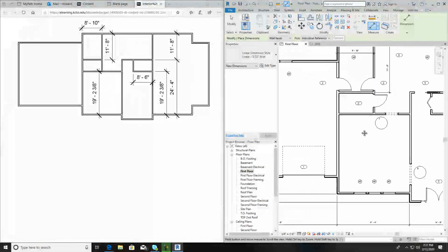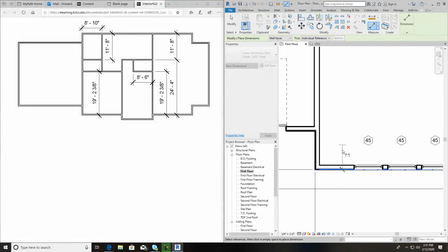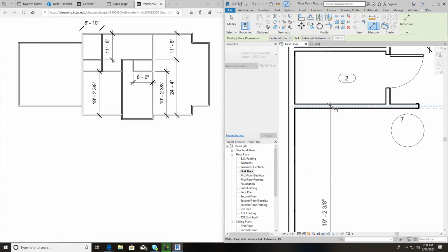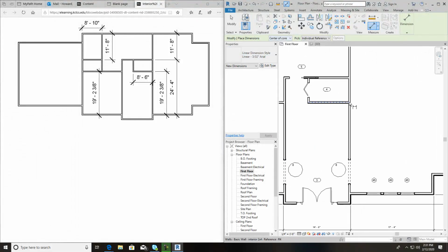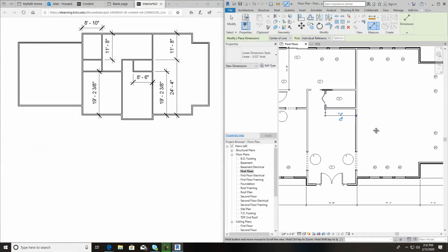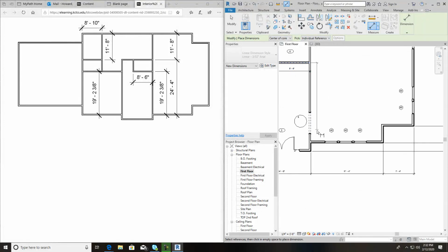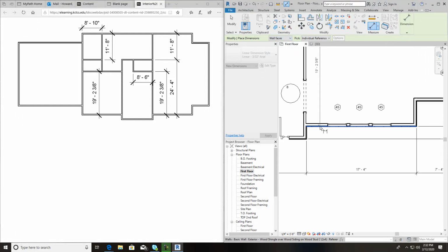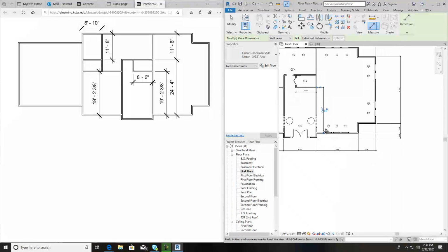Now, I back it up. I want to check from that to my center core here. It's beautiful. While the center core is on, we can grab that. 8'6", that's right on the money. And then we've got down from here, the center core to the wall face right there. And we are seeing that at 19.2 3/8. That's perfect. That's absolutely perfect.